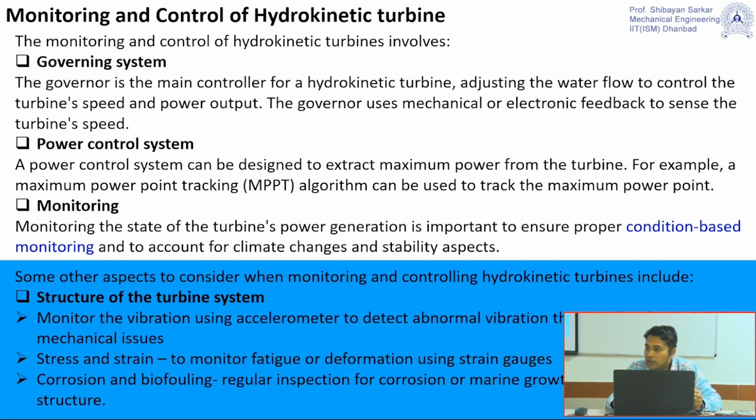So, structure of the turbine design. I told you that this type of turbine is very prone to failure due to fatigue, or it may be clogged, or it may have some other problem leading to failure. Cavitation problems may occur. You can observe this failure through the strain gauge, or some other monitoring system surrounding this turbine. You can put some underwater camera surrounding this particular site, which can give you a live feed of what is happening around the turbine. Or maybe the turbine has been stopped.